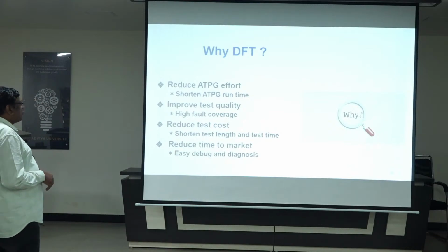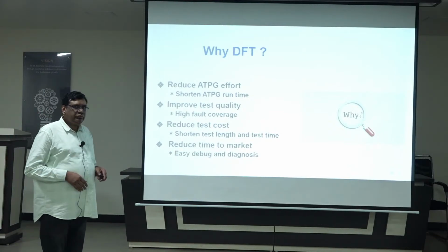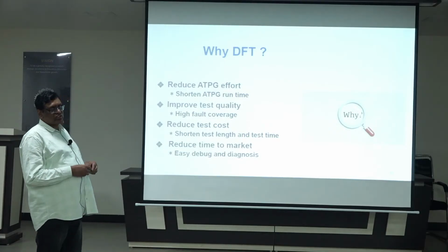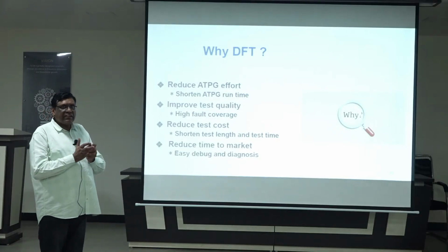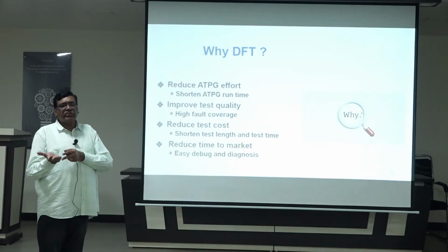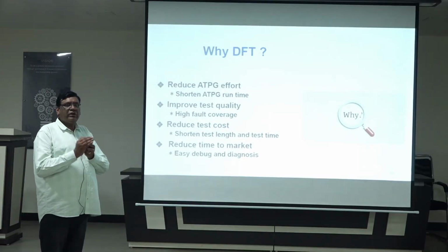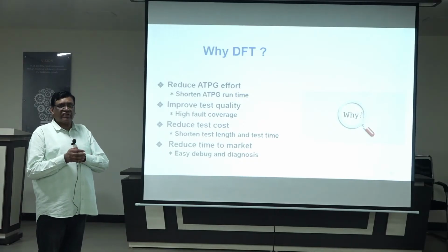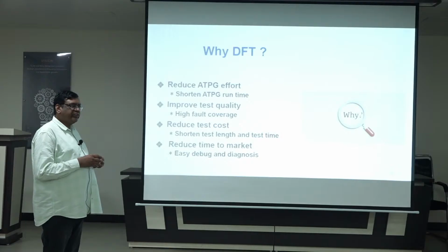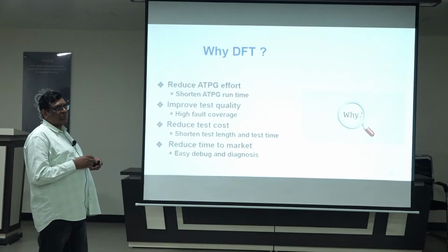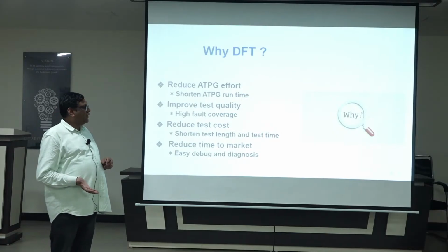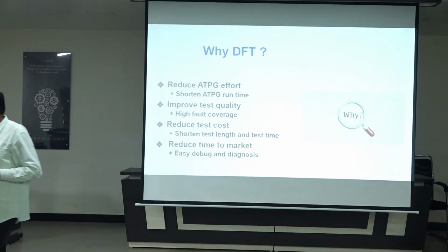Okay, improve test quality. Obviously the reliability of the chip will be improved. Reduce test cost. If the number of patterns is less, test time on the ATE machine, which is very costly, is less. How much time you hire the ATE machine, that much cost will be there, but with DFT the test cost will reduce. Then reduce the time to market. How fast you can deliver the product to the market, that also can be reduced by using DFT.